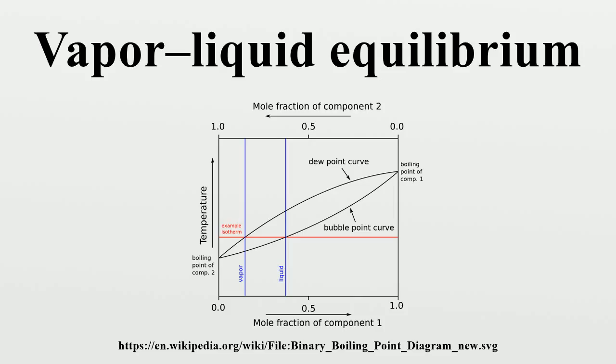Alternatively, the three-dimensional curved surfaces can be represented on a two-dimensional graph by the use of curved isotherm lines at graduated intervals, similar to iso-altitude lines on a map. Two sets of such isotherm lines are needed on such a two-dimensional graph. One set for the bubble point surface and another set for the dew point surface.